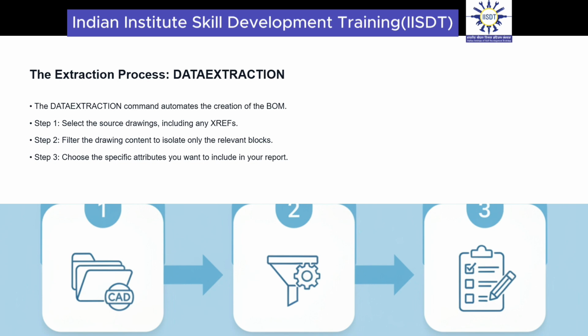The process begins with selecting your data source. You can choose the current drawing or you can select multiple drawings at once, which is incredibly useful for project-wide reports. Crucially, this is where you tell the software whether to include the data from any attached XREFs to ensure you capture everything. The next step is filtering.